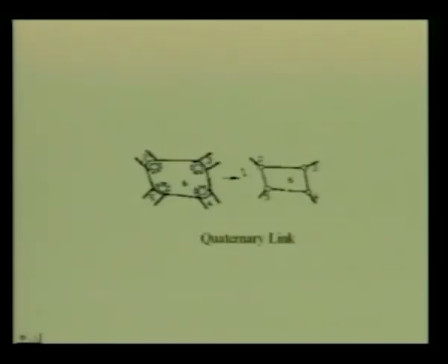This diagram shows how higher order links must be represented. Here, as we see, link number 2, 3, 4 and 5 are connected to a quaternary link which is numbered 6. Since link number 6 is connected to 4 other links, this is a quaternary link. In the kinematic diagram or the line sketch, if it is represented like this, then there is ambiguity. One may interpret that at this revolute pair, 3 binary links, this one and link number 4, are being connected.